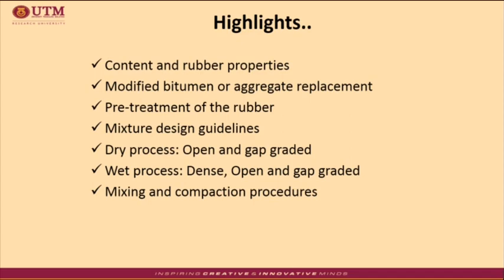For the mixture design guidelines, a few elements should be put under consideration, such as aggregate gradation, bitumen content, and air voids content. In dry process mix, normally the open graded and gap graded are more preferred, while for wet process mix, the modification is suitable for dense graded, open graded, and gap graded mixture.